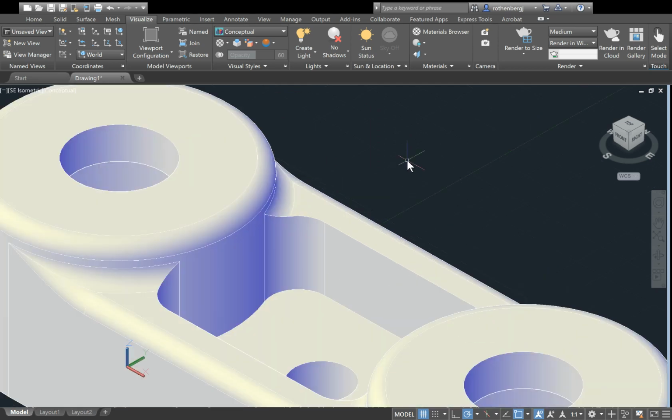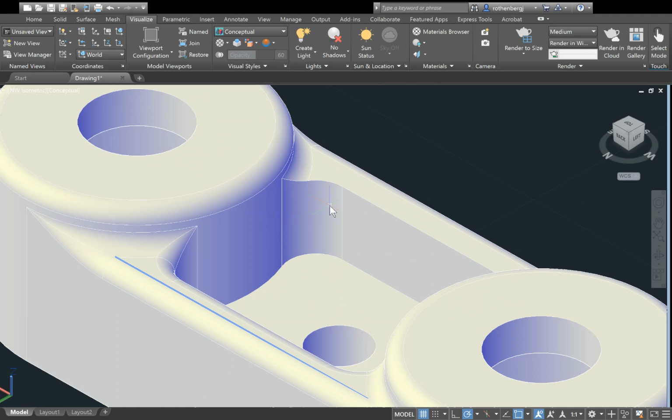So now fillet once more, select this inner edge now, and we'll follow the same way to do the chain command. So hit enter, C, click, enter, go to the other side, fillet, click, enter, C, enter, click, enter, and that's good. We're basically done. Now we just have to do the inner edge. So select that, enter, C, enter, click, enter, and that got the whole interior.